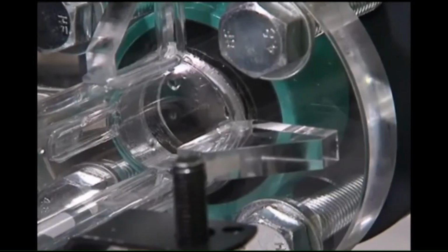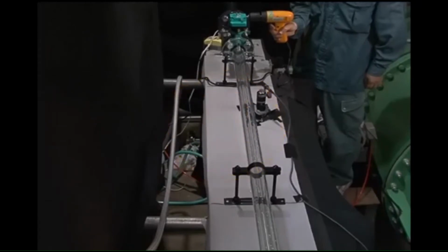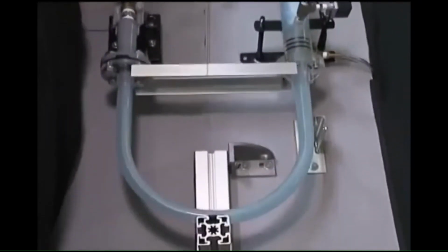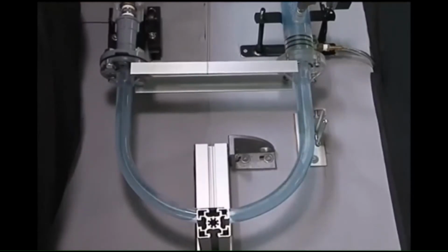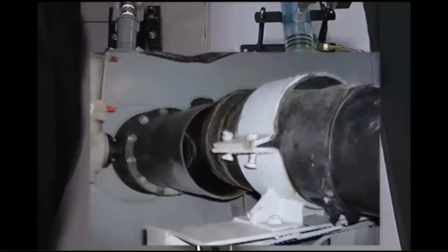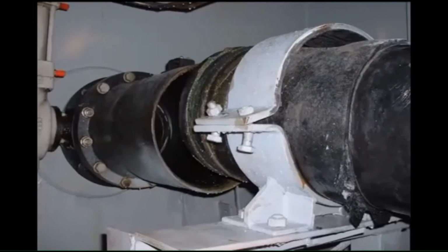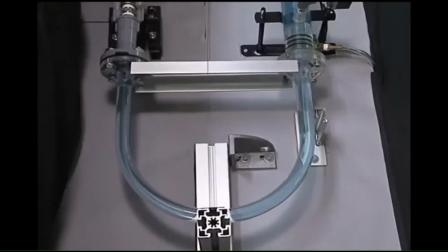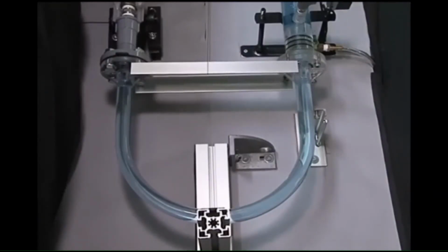First, let's look at a case in which the butterfly valve is fully opened suddenly. The U-tube is movable. When pushed by the water force, it moves back and absorbs the impact. With an actual pipeline, such impact cannot be absorbed fully, resulting in damages such as cracks. Damage to the dresser joint is typical. Now we'll review this process using an image simultaneously shot from 3 directions.